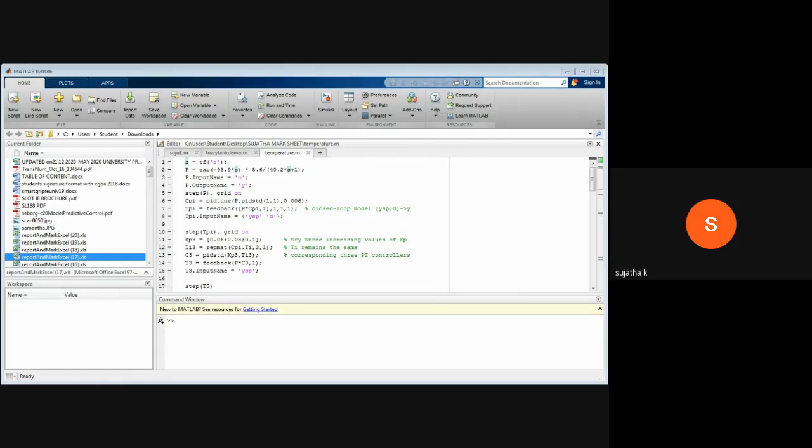Now you are going to build an on-off controller. For building the on-off controller, first you require an input. So go to commonly used blocks. By going to commonly used blocks, you have to take the block called constant. From the constant block only you are going to give the input. Simply drag and drop, and you will get the constant there.